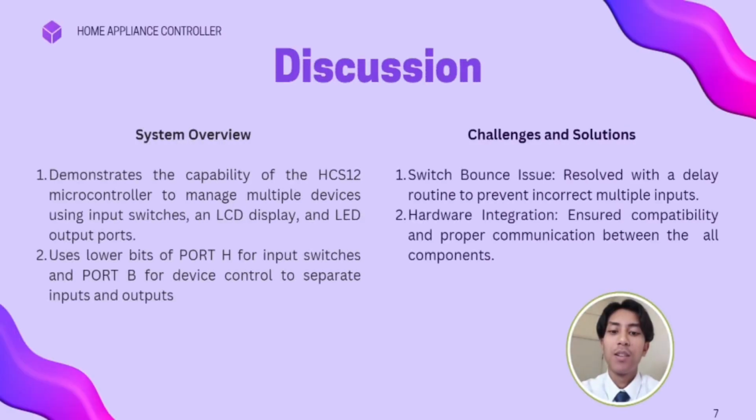Moving on to our discussion of the project, a bit of system overview. We successfully demonstrate the capability of the HCS12 microcontroller to manage multiple devices using input switches, LCD display and LED output ports. Secondly, we use lower bits of port H for input switches and use port P for device control to separate inputs and outputs.